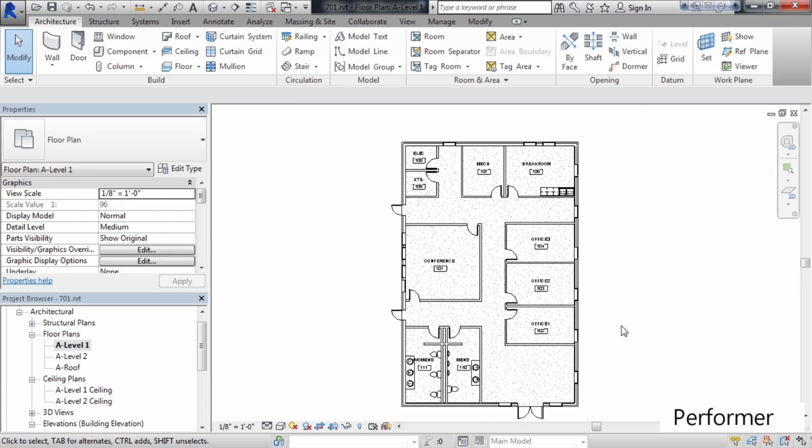So as a review, what we covered in this lesson was rooms and room tags. We looked at different ways to place rooms and their tags. First off, by just creating a generic room label and having a room number sequentially count up. Once we placed that room, we manually edited the name of that room and/or number.